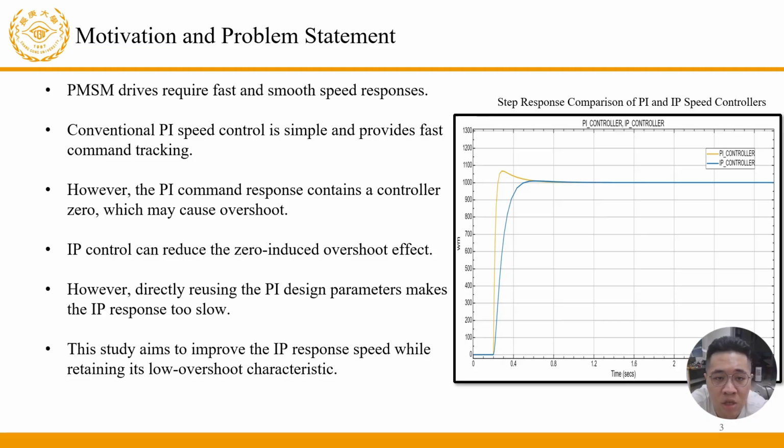when the speed command changes. To reduce this overshoot, the IP controller can be used. The IP structure can reduce the zero-induced overshoot effect. However, if the IP controller directly reuses the PI design parameters, its response becomes much slower. Therefore, the main problem of this study is how to improve the response speed of the IP controller while keeping